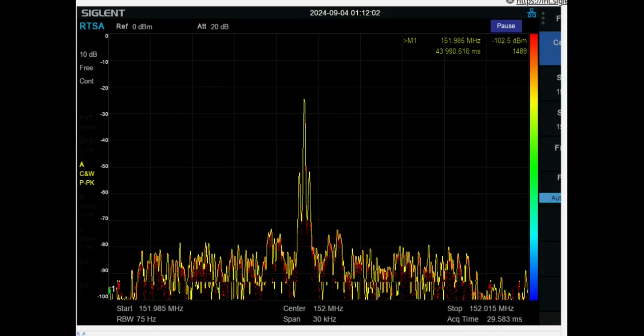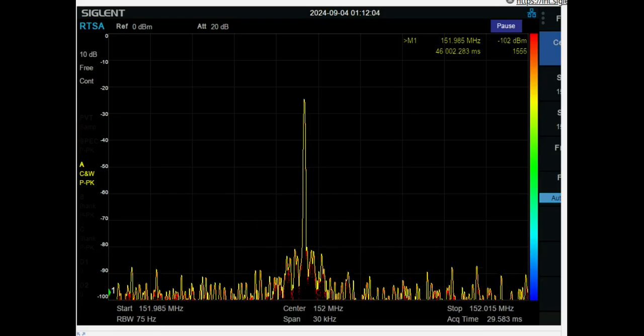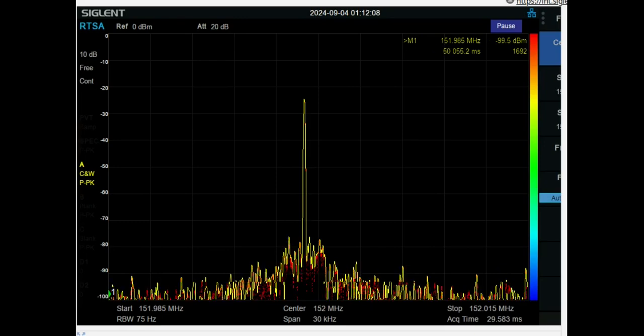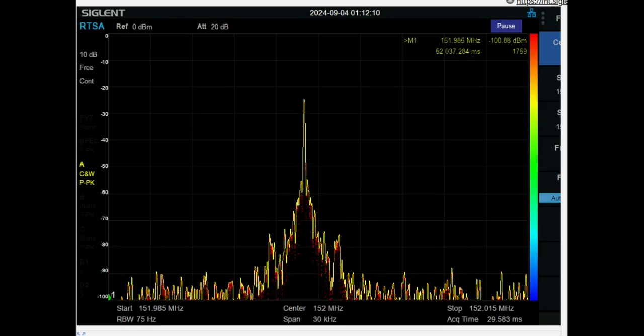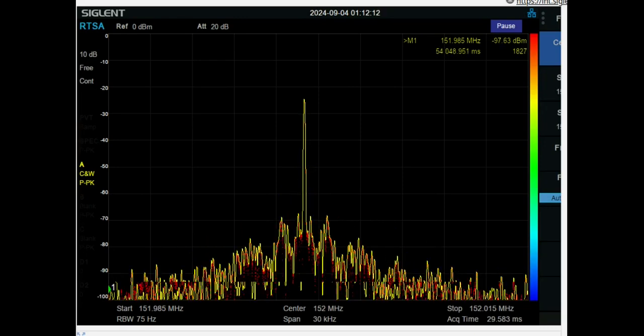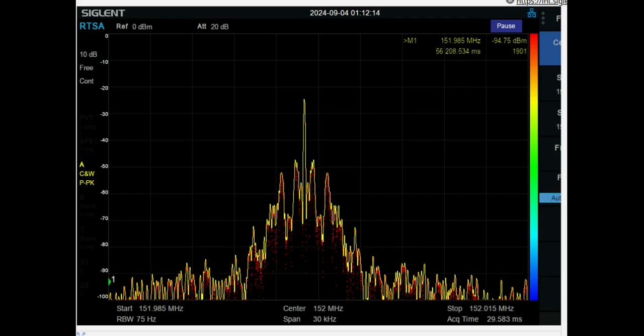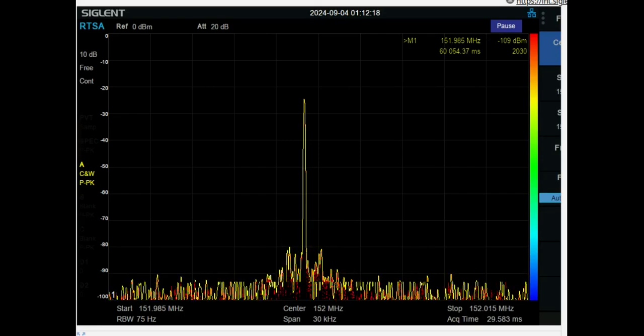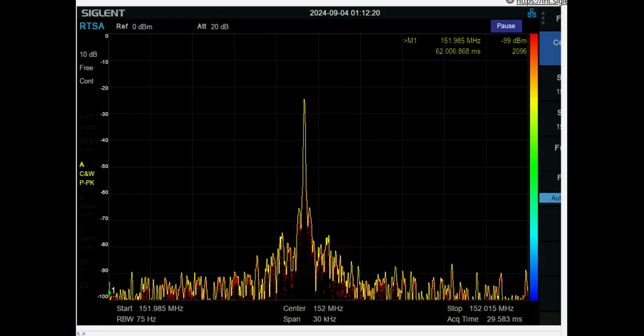So definitely want to get the low pass filter on the output of this thing. Or if you want to do VHF, you could use these Nyquist zones as I'm showing you here. Again, how did I get 152? It's simply 27 plus the DAC clock, which is 125 megs, and that summation works out to be 152.